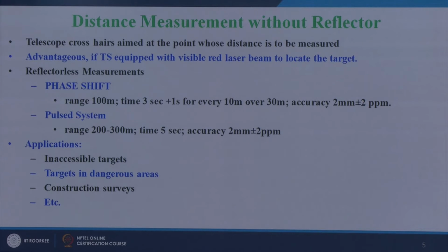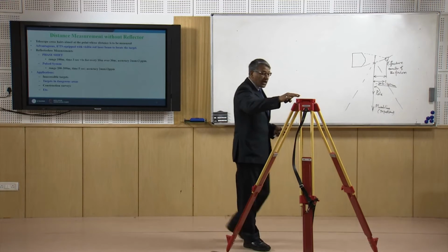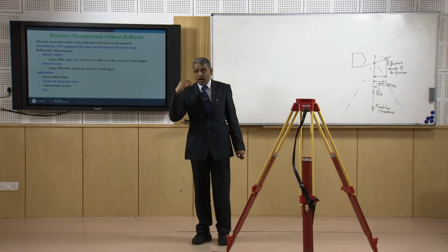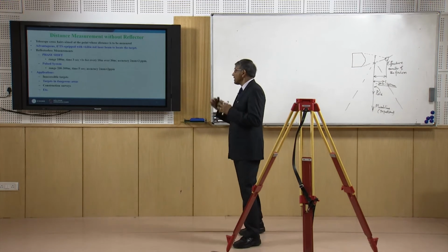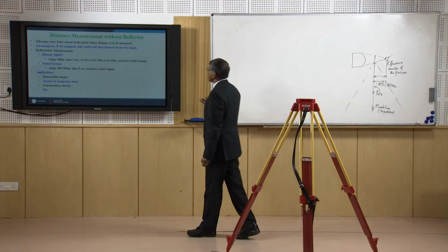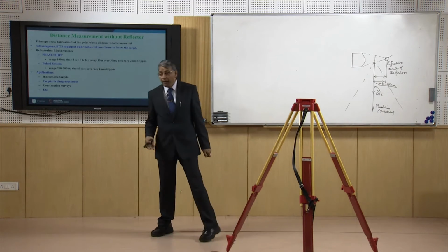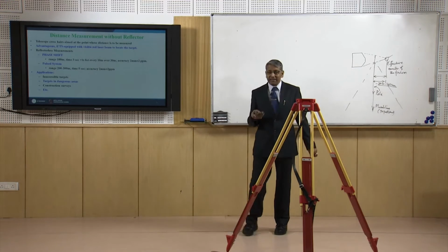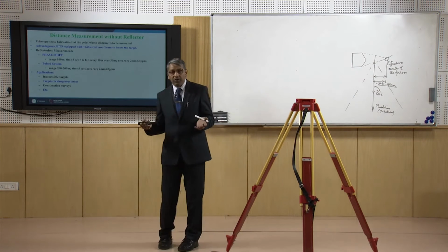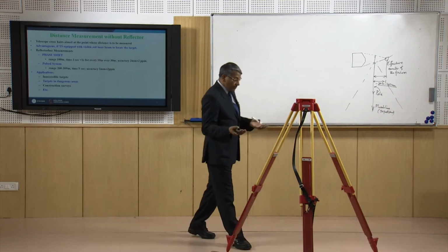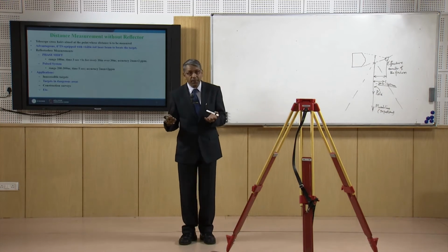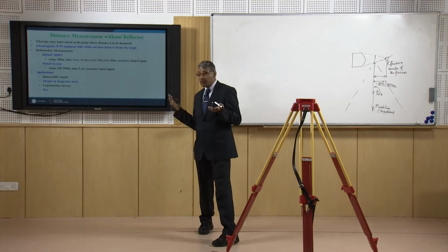Now, there is another way you can measure distance using the total station, that is called reflectorless. That means we can directly take the reading using the total station to the object without having any reflector. So, this is a method of taking measurement which is now getting very popular because of many reasons. First point is that as we will not be using the reflector, the number of persons involved in surveying will be less. There will be many times when the points or the measurement location is inaccessible. In that case, reflectorless is a very good one.